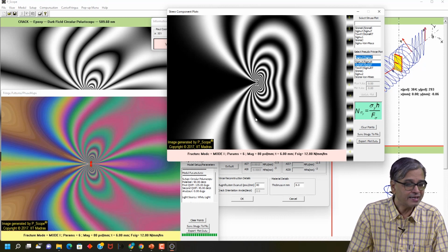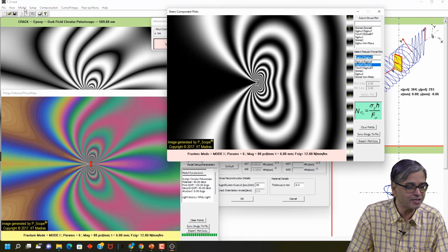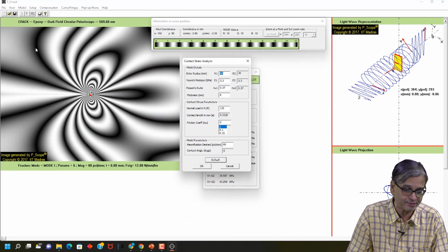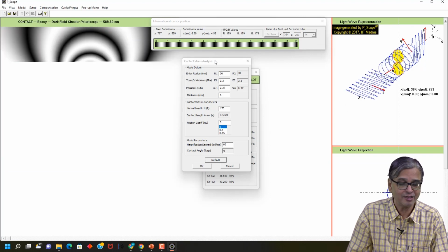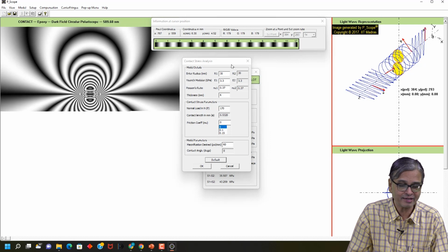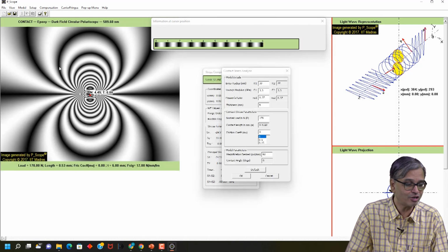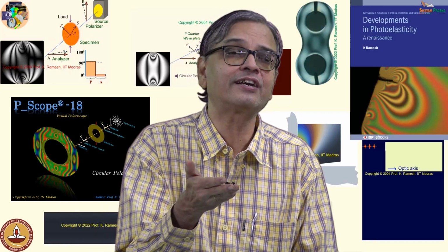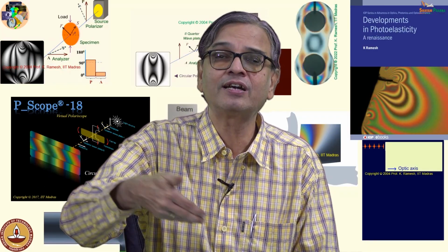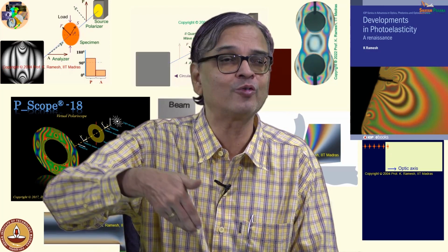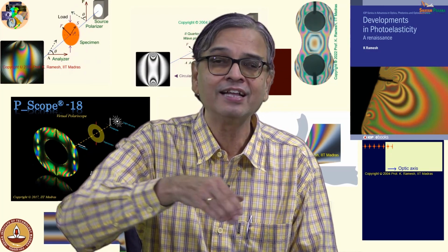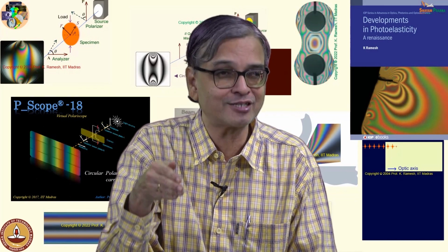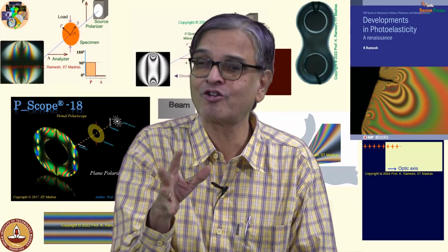Okay. Then another interesting problem that is not normally taken up even in your second course, but is very important, which happens even in the case of simple railways, is this. You have what is known as contact stress. Whenever you have a concentrated load, the concentrated load is actually happening over a small area. I also showed an ellipsoidal distribution. That's known as Hertzian contact.